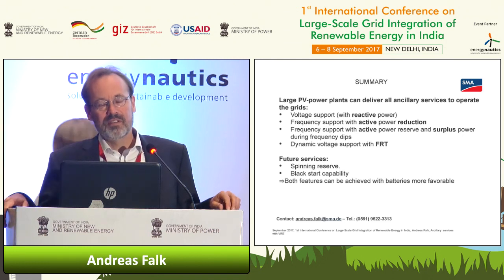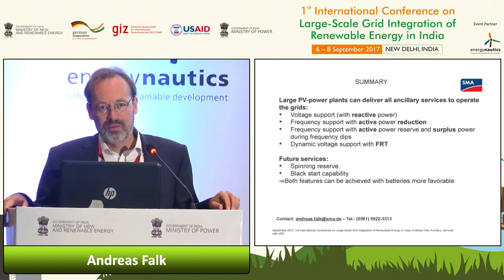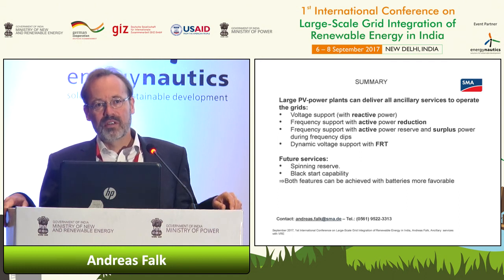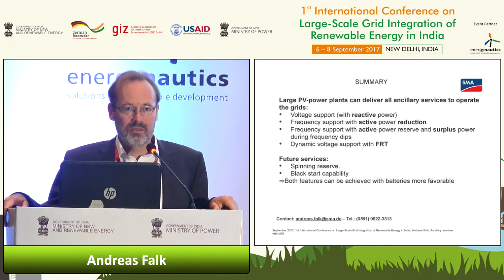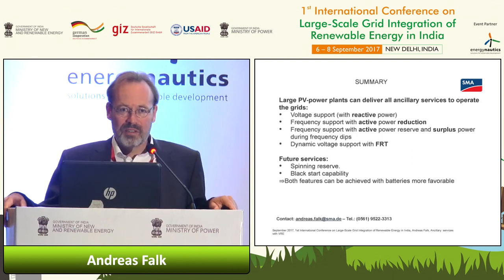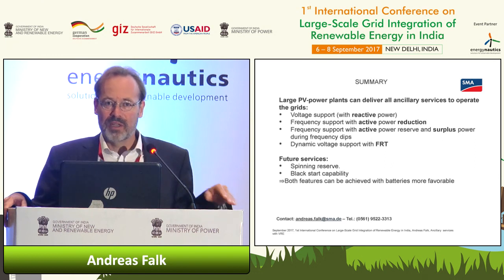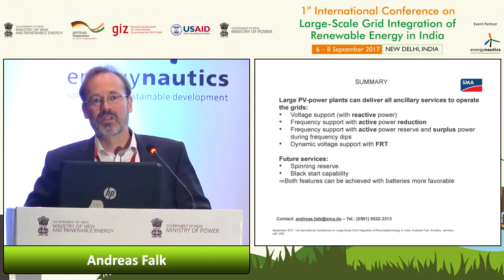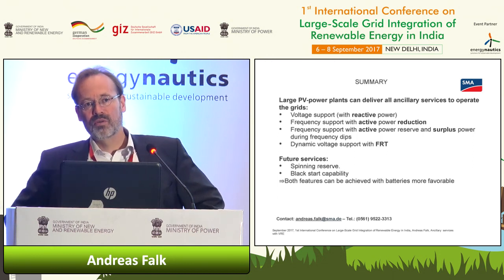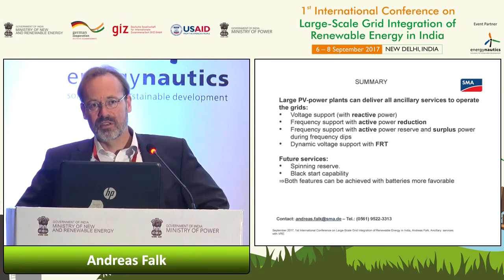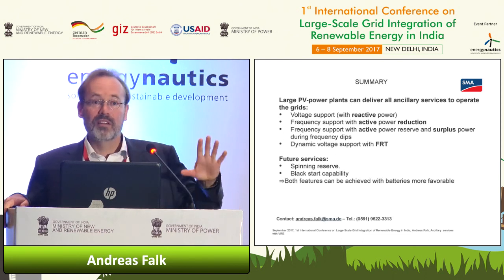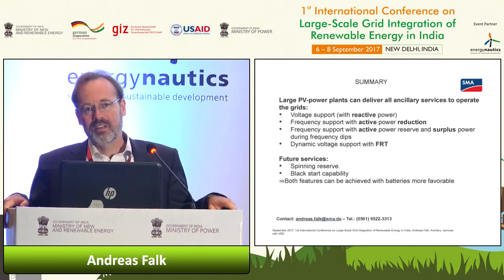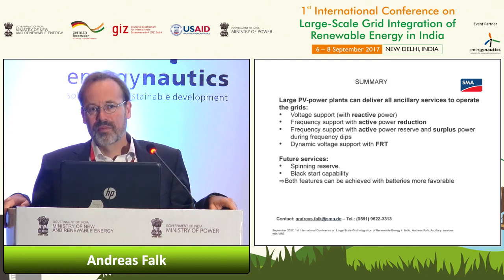There is a difference regarding spinning reserve. A spinning reserve is provided from synchronous generators only at the moment, but the ability of the renewables will become better and better, and in the future, when you have more and more voltage controlled units and not only current controlled units in the grid, also the spinning reserve can be provided from renewables, and that is visible in only, let's say, 2 to 5 years, not more. Okay, thank you.